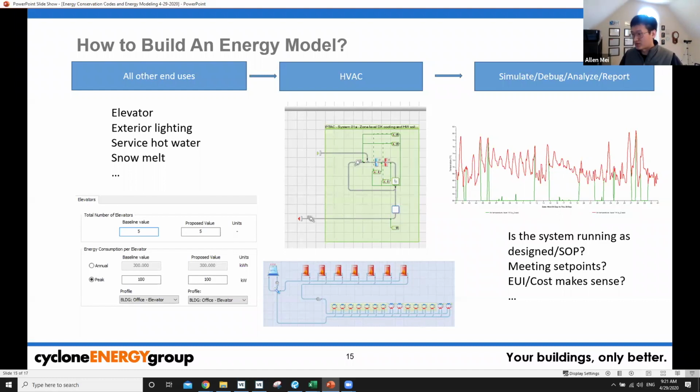And what is the supply temperature of this cooling coil? Do you supply 55 and reset that to 60? Or do you just supply constantly 55? Things like that. And what kind of pump control for your condenser loop? Those are a lot of detailed inputs and a lot of thinking behind this HVAC.